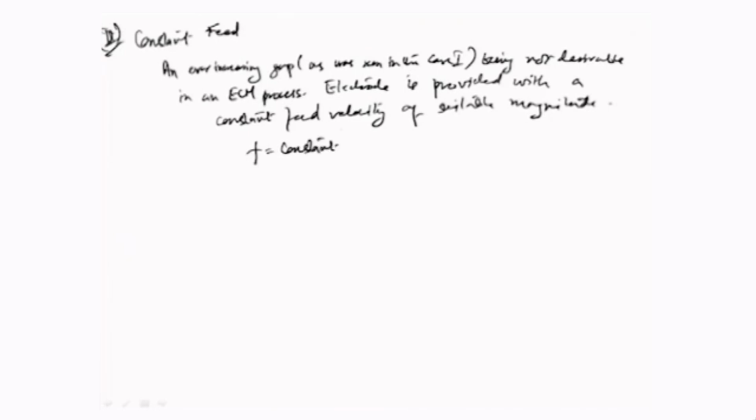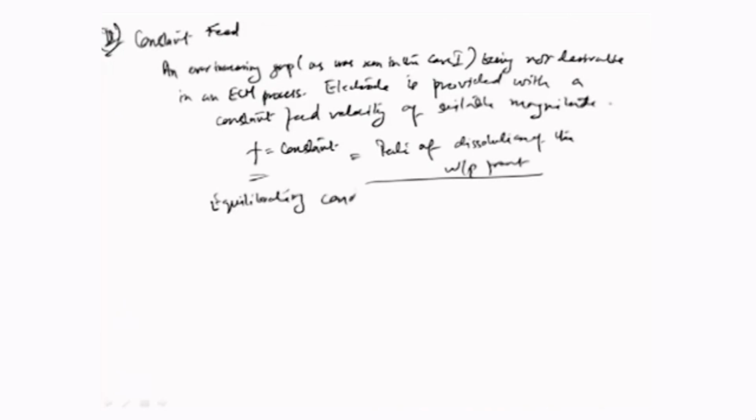So, what eventually would happen is that there would be a case where the feed becomes equal to the rate of dissolution of the workpiece front. In other words, there is an equilibrating condition which would arise.